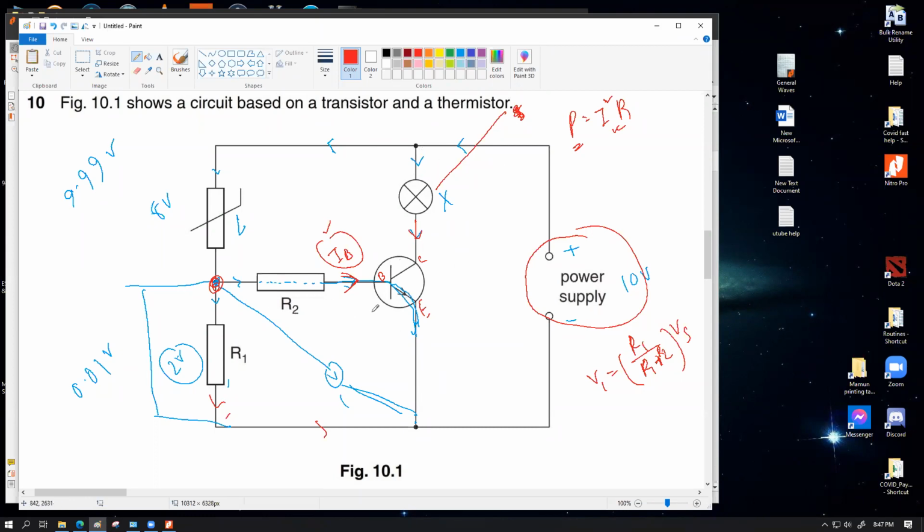Or if you allow, let's say, half ampere through here, 50 ampere can pass through. Or if you apply 0.1 ampere through here, 10 ampere can pass through. It's going to maintain that ratio of 1:100 to maximum. But to make that current flow through this branch, you need to make sure that the required voltage supply is connected to make sure that current flow exists.